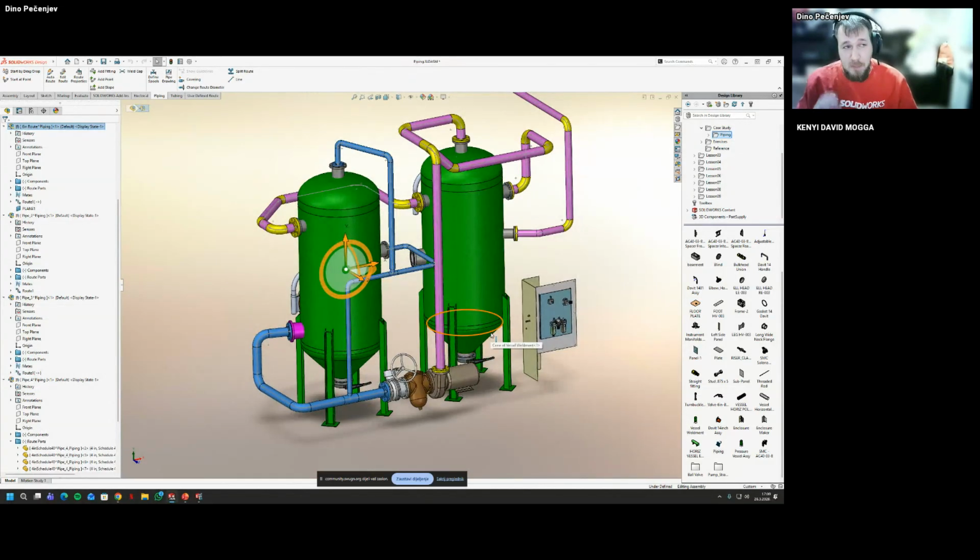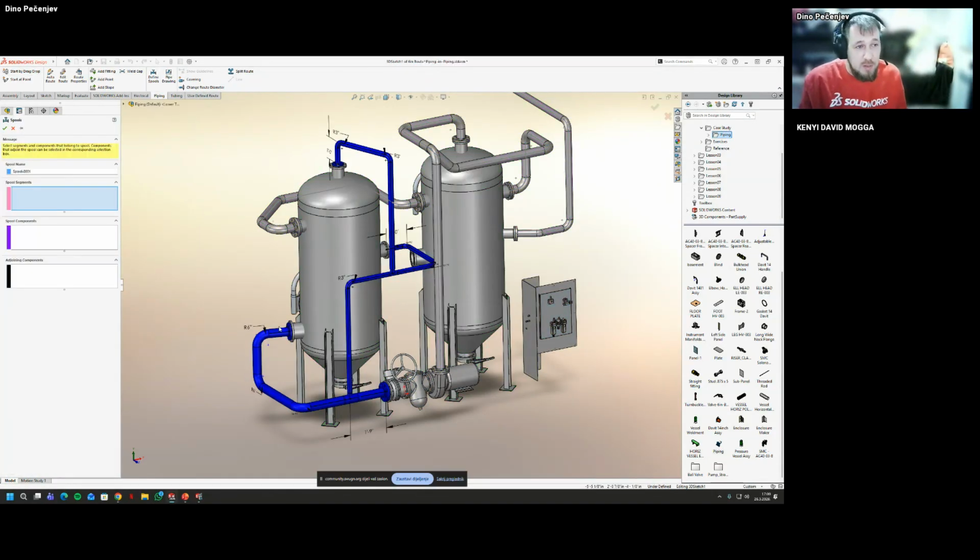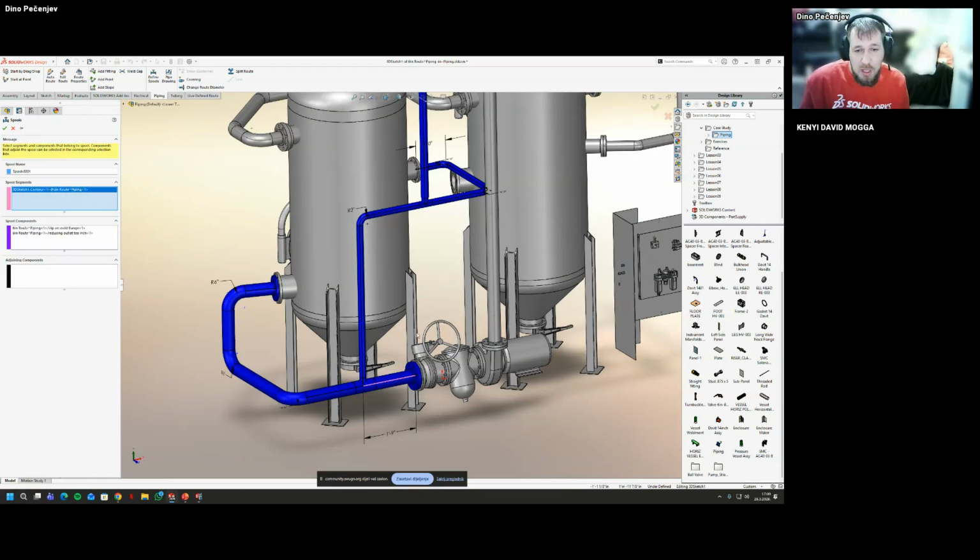This can be a mess when we want to clarify how our information is shown. So what we're going to do here is define spools. Let's say in the spool I want this part of the section, and it will automatically grab also this auto T. I can remove it and use it for the next section. So this will be an easy part.